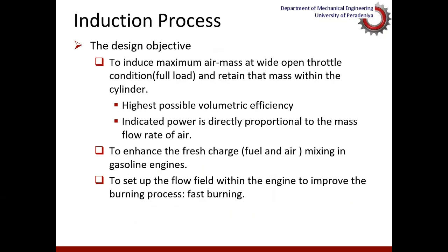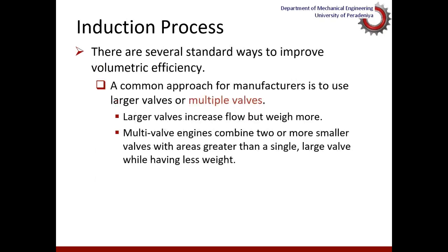Also in the intake system, we need to make sure that the air and fuel mix well during the induction process, particularly in spark ignition engines. And we'll need to create certain turbulent flow patterns in order to enable proper mixing of air and fuel during the intake process as well as the compression process. If you can recall, we generate swirl and tumble flow in the intake system just to enable that. Those are the important things that we need to consider when it comes to